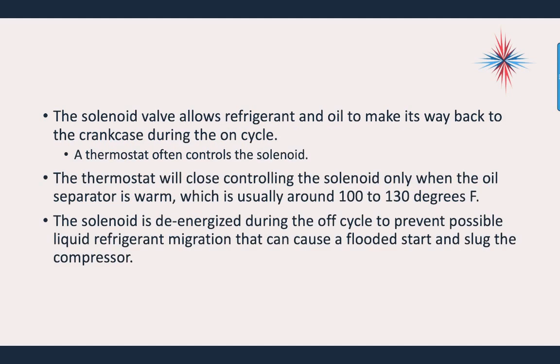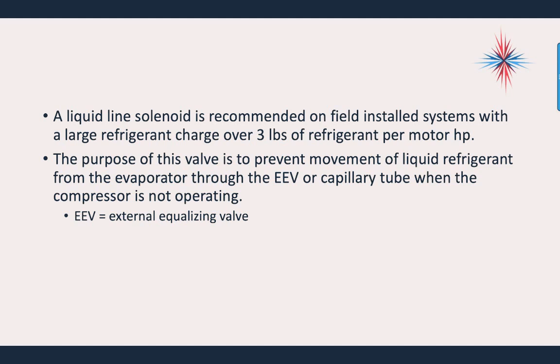The solenoid allows the refrigerant oil to make its way back to the crankcase during the on cycle. The thermostat will close, controlling the solenoid, only when the oil separator is warm, usually around 100 to 130 degrees. The solenoid is de-energized during the off cycle to prevent possible liquid refrigerant migration that could cause a flooded start or slug the compressor. A liquid line solenoid is recommended on field installed systems with a large refrigerant charge over 3 pounds of refrigerant per motor horsepower.